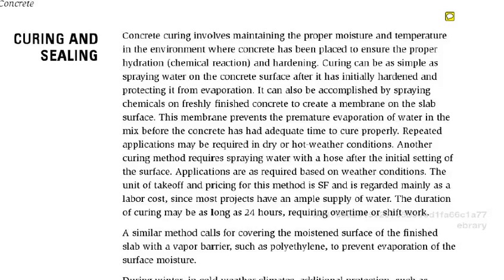Then you're going to spray it down with the curing compound. It's that white spray that you see on concrete. There also are clear curing compounds. I always prefer white because I can see how it's been applied to the concrete, if it's been done uniformly and if anything's been skipped. So it's a quality control item.